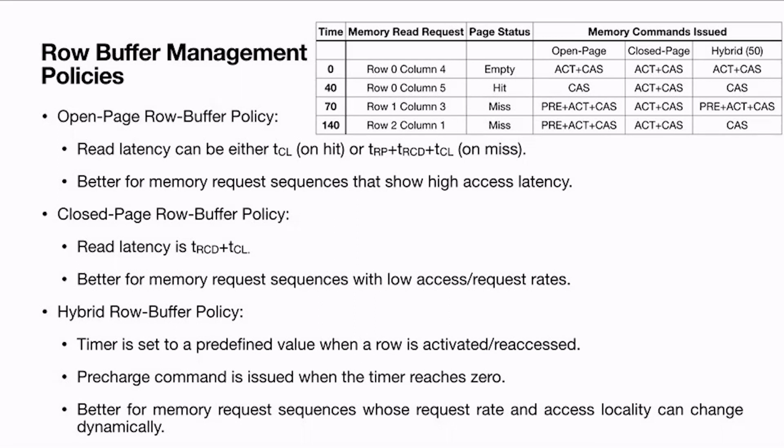But you cannot give a strict rule saying that the data is going to be placed in a particular location, and then exploit the locality. You cannot force the memory controller to do that, since the memory controller is responsible for spreading out the data in the DRAM. Is it the memory controller only which does this address space randomization? Yes.